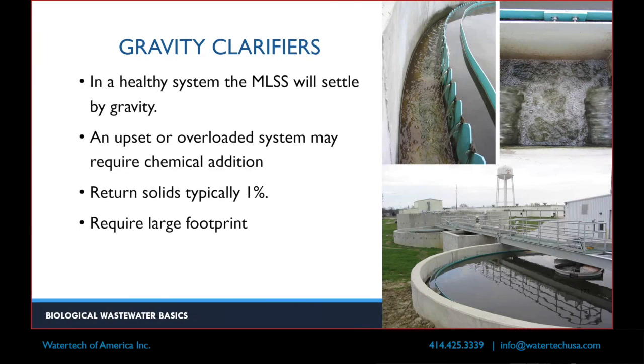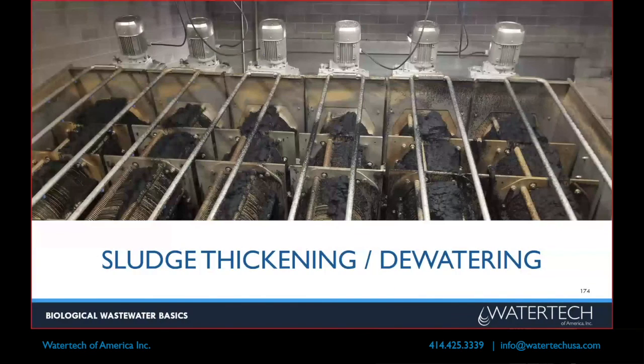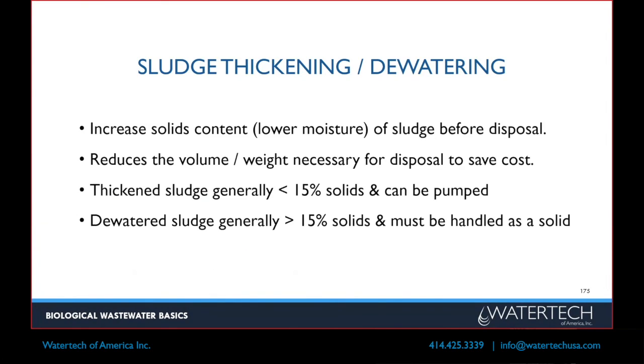This place had acres of retention ponds behind it. So they just took their 1% and they dumped it in their pond and no problem. Places that can't handle that volume, if it's only 1% and you have to haul it, you're going to be doing a lot of hauling. So in those types of instances, having the ability to thicken your biosolids is going to, there's a cost of operating this, but you're saving on the side of how much you're having to haul. So that's the purpose of these.